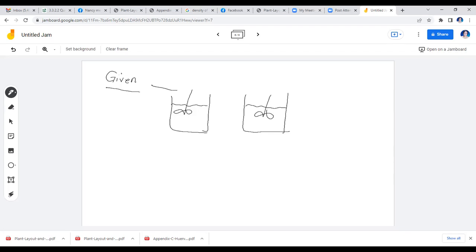So you have one feed here, and then the discharge from the first is being processed in the second, and you have this one as the last. So in here, you have your initial concentration, and you have also here your molar feed rate. But since the problem does not give it, we will not label it that way anymore. You have here CA1. This is also CA1 here, the concentration inside your first CSTR, and this is your CA2.